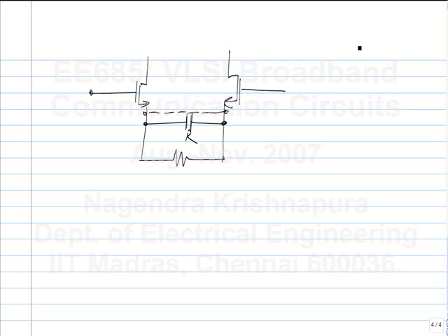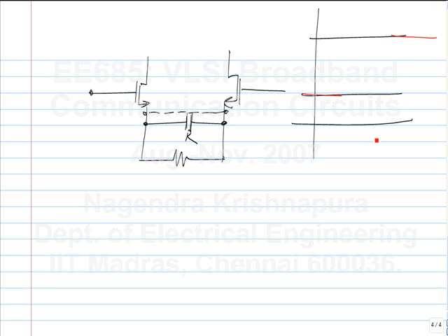Let's say the gain of the differential pair was this, that is when the sources are shorted, and when you degenerate it with the resistance, it falls down to this, and when you also degenerate it with the capacitance, it has to be this at low frequencies and this at high frequencies, isn't it? For those frequencies where the capacitance is short, the gain is this. For those frequencies where the capacitance is open, the gain is this. So it has to go from here to here. Is that okay or not convincing?